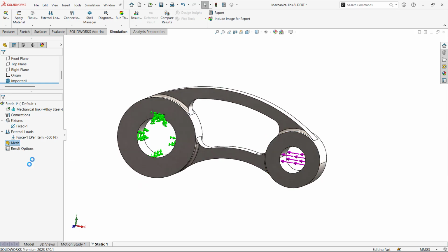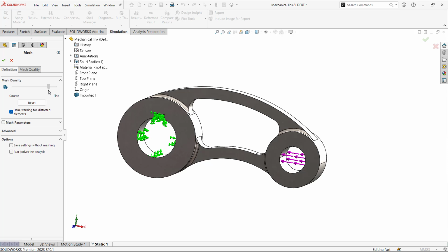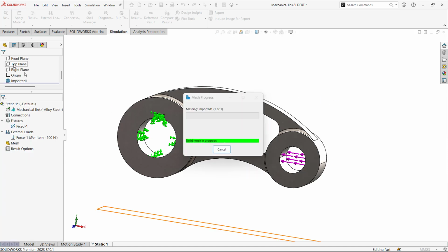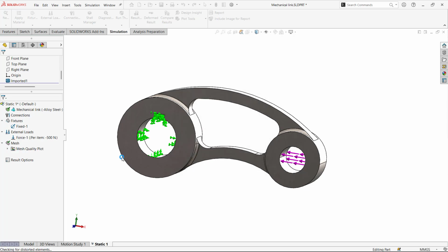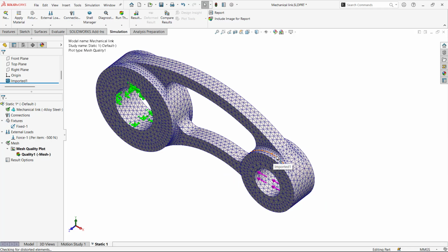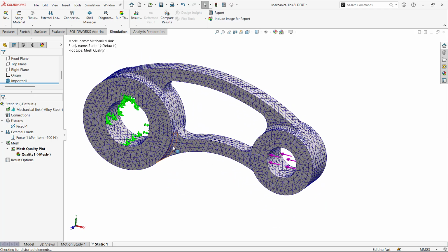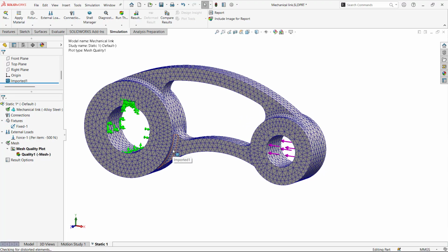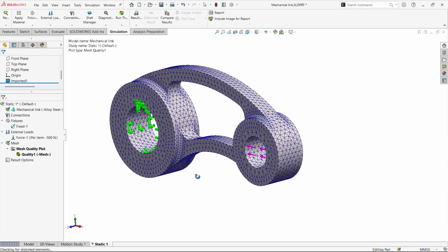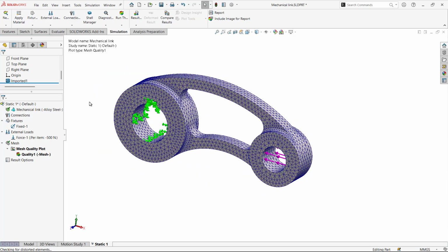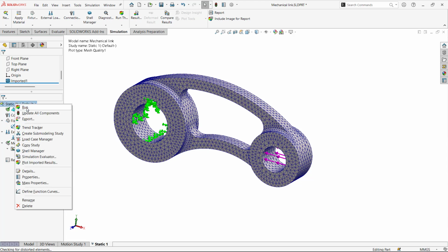Now I'll need to mesh this model. I'll go ahead with a slightly fine blended curvature. This time I would like to use 3. Grain check. So here I do need the curvatures. I don't need to do the geometry cleanup on this model, because due to the buckling or due to the load cases here, we might get stress hotspots, so we should have the curvature radius there. Now this is fine.